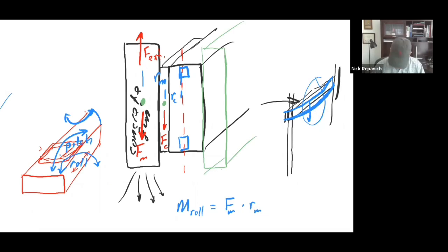So they would be mounted to it. The green thing I just drew is supporting the main deflection from the overall mass of the unit. All these bearings have to do is travel a straight distance, and they have to worry about the moment loading. As you start to look at choosing, you would only have one or two of the moments in static, and then when you start to move things around, they change to a different moment.